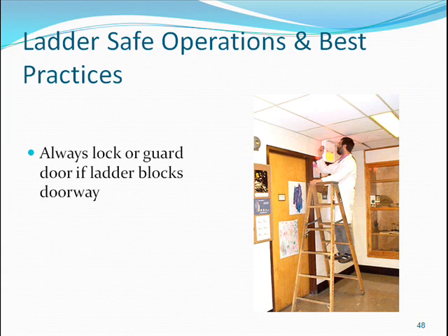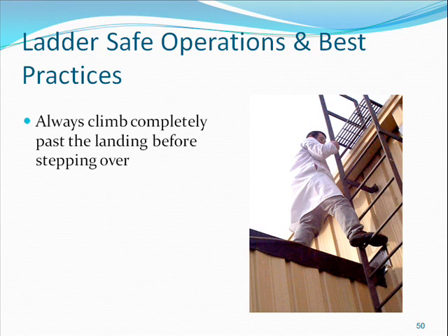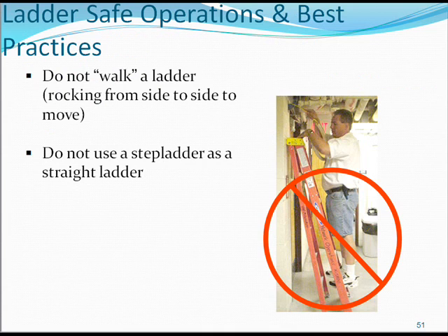Ladders placed in areas such as passageways, doorways, or driveways, or where they can be displaced by workplace activities or traffic, must be secured to prevent accidental movement, or a barricade must be used to keep traffic or activities away from the ladder. Use extra caution while climbing in windy weather. Always climb completely past the landing before stepping over. Do not walk a ladder, rocking from side to side to move.